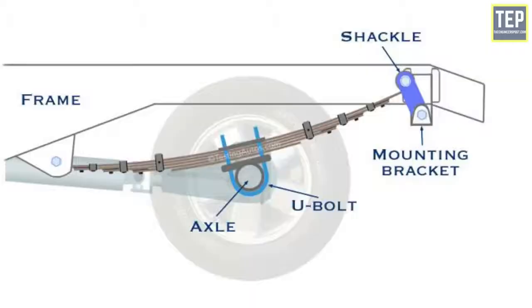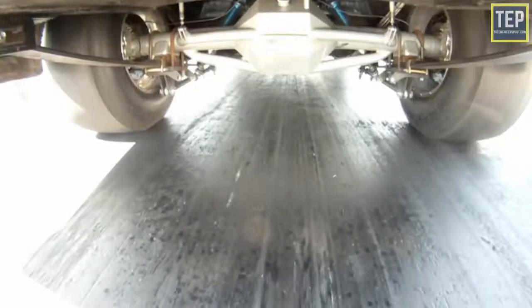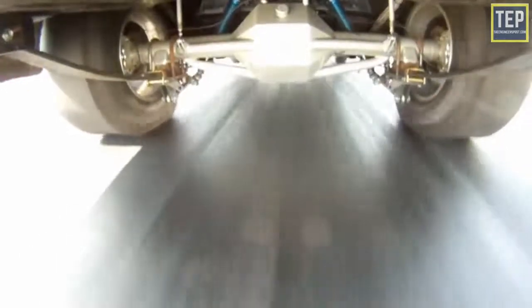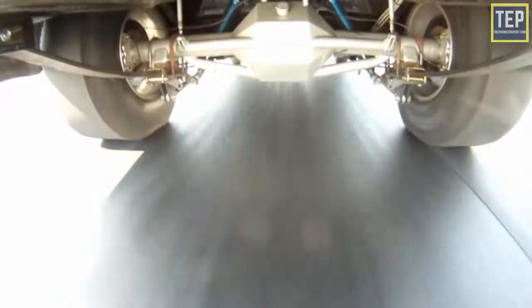Also, the shackle includes a rubber bushing, which absorbs vibrations and prevents them from reaching the vehicle. The center portion of the leaf spring is attached to the rear axle housing with the help of U-bolts, and a rebound clip holds all the springs together. This type of suspension is used in trucks, intended for more severe operations, and with rear axles with high payload.